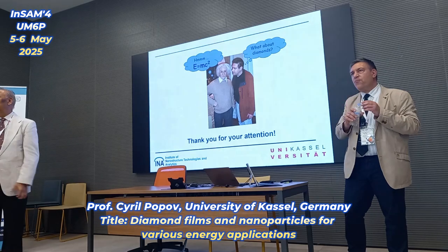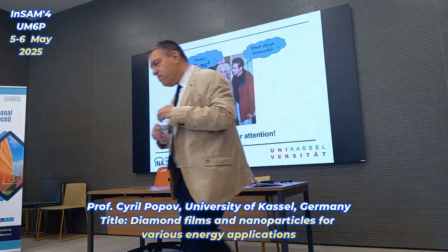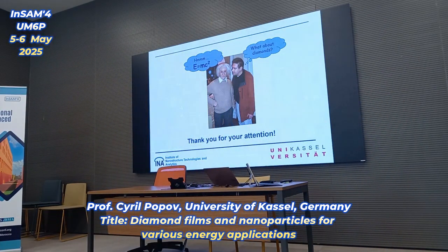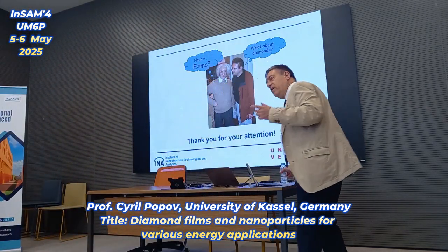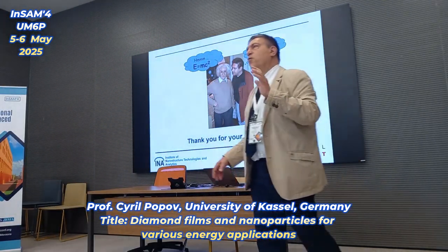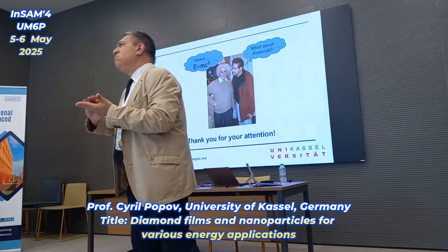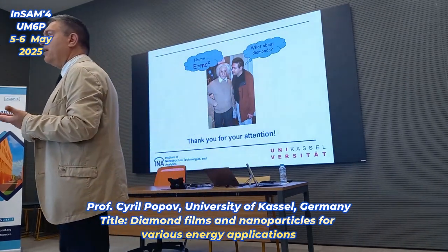Yes, sir. Thank you very much for this presentation. I just have one question about UNCD films. Do you have any idea about their adhesion? That's the most important. Adhesion, I didn't mention because it's a complex topic. Adhesion is good on substrates which can form a monolayer or a few monolayers of carbide.